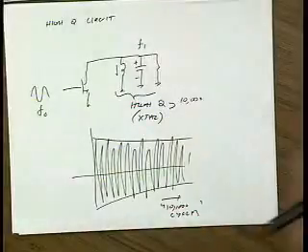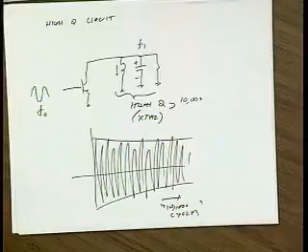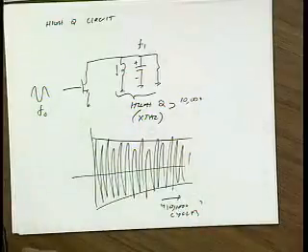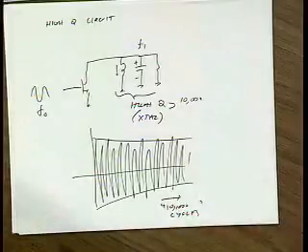Okay, I think I have a question back here. So what if you have multiple tones in your system and they're not integer multiples of the other frequency? What's the period? Well, you still get the beat frequency, right? No, 1 megahertz, 3 megahertz, 5 megahertz. Yeah, it's basically never goes into true periodic steady state. It goes into quasi-periodic steady state. And there is another analysis inside Spectre to handle those kinds of circuits. Okay, good, very good question.